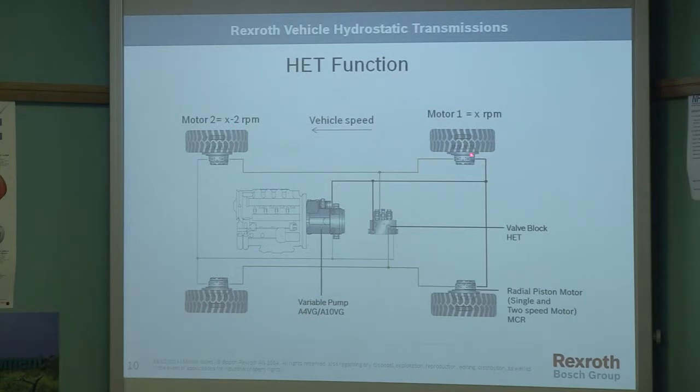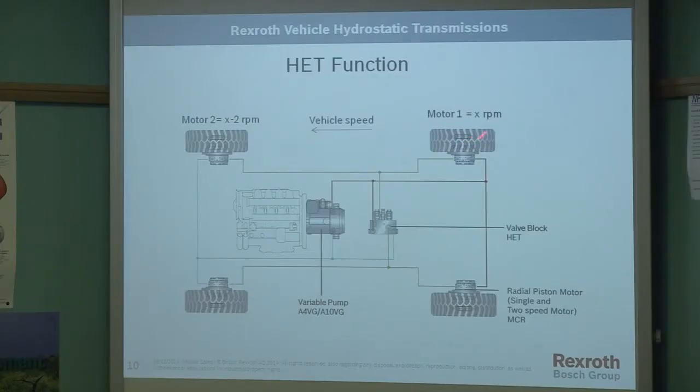And this isn't just on construction equipment or hydraulic vehicles. Normal car wheels will slip, as it's called, 1 to 3%. Now when I say slip, I don't mean skidding or spinning. This is the rotation of the wheel is fractionally lower than the vehicle would indicate because it's transmitting the torque or creating the traction.